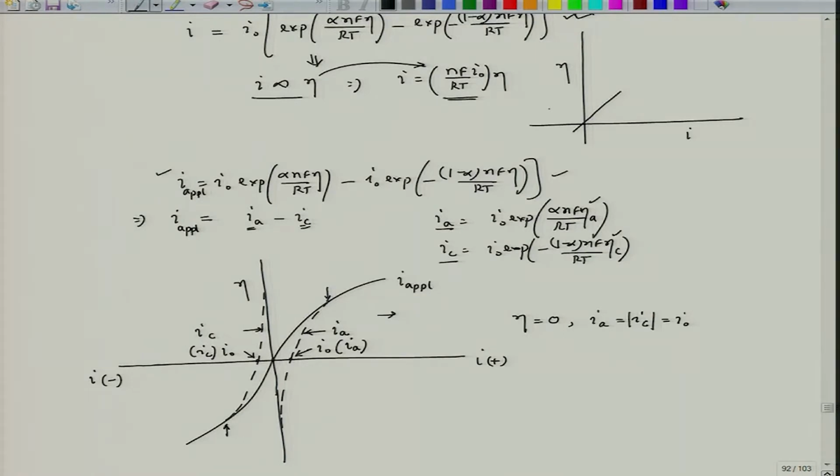This is also understandable, because if we see the Evans diagram, we have seen that this was the over voltage plot, this was I 0, and in this case it was in the log scale, isn't it. So, the polarization plot was like this, and as we go upward, since it is a log scale, the influence of this quantity on this will be extremely low.